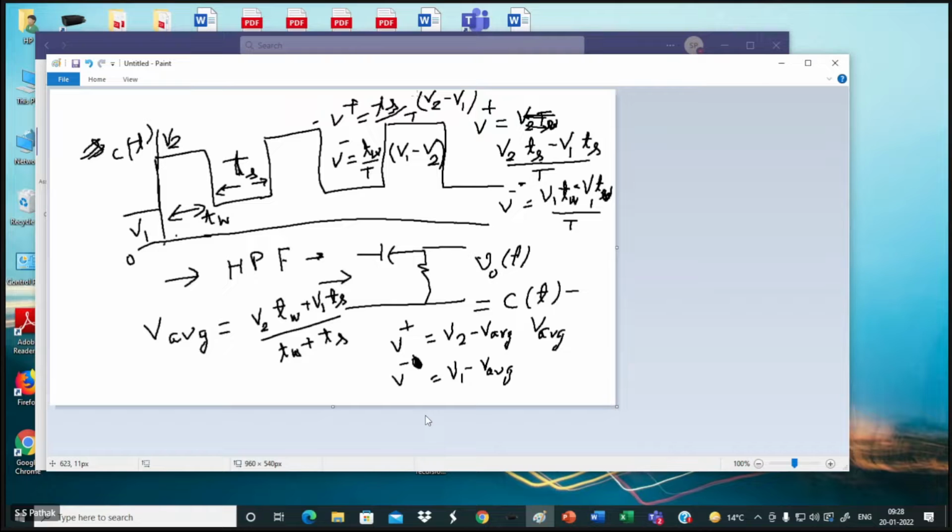The average will be subtracted from there. It happens only in the high pass kind of architecture, where every contact point we consider as having a capacitive effect. One series capacitor coming on the way becomes a blocking capacitor, a DC blocking. So DC is blocked, every average is blocked. And this is the amplitude of the pulse that is appearing here.